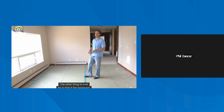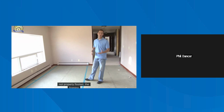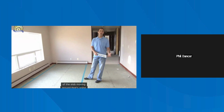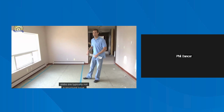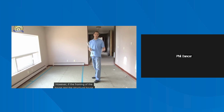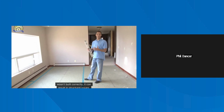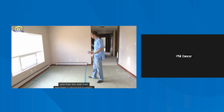The other thing to look for is, if the basement is finished, if the walls are properly floated. If they're not properly floated, the framing is going to move as a direct result of the slab moving around. That's going to be connected to the floor joists, which is then going to be affecting the main floor. So slabs are typically not a structural issue. However, if the framing and the structure of the house wasn't built correctly, it can result in structural issues, and then the slab becomes a structural problem.